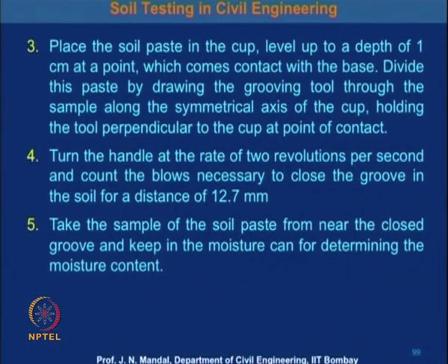Now, take a sample of the soil paste from near the closed groove and keep it in the moisture can for determining the moisture content of the soil.